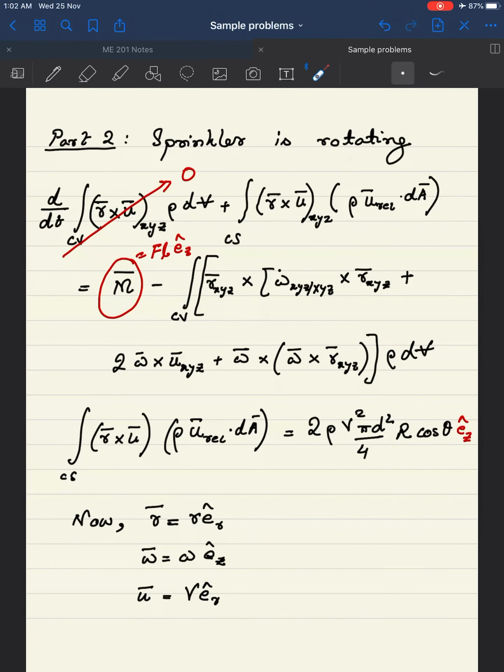So if you have to do that, then you have obviously all the previous terms, but the new term that you have is this, right? And I hope all of you remember where this comes from. This simply comes because of the rotation of the reference frame attached to the non-inertial control volume compared to the inertial reference frame. And let's say the inertial reference frame is capital X, Y, Z, and the non-inertial reference frame is small x, y, z. So all these terms are there.